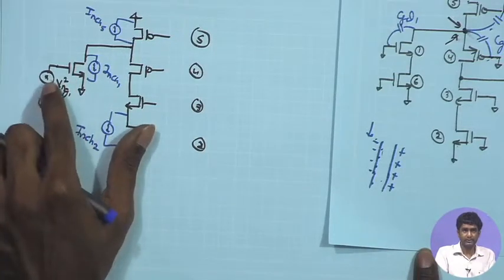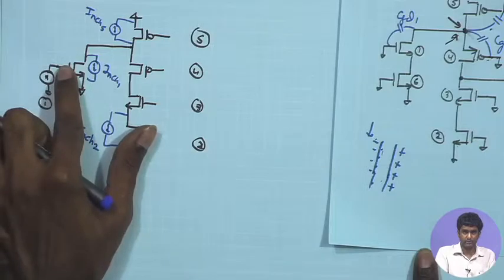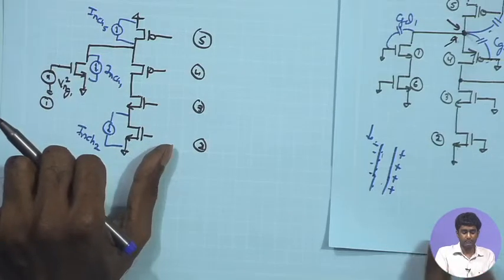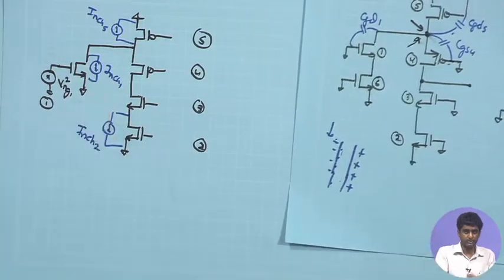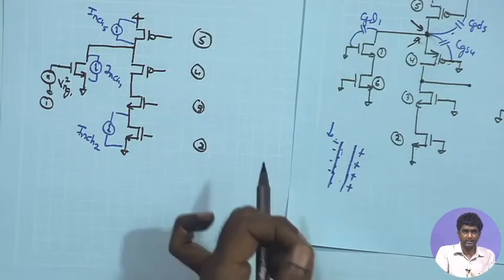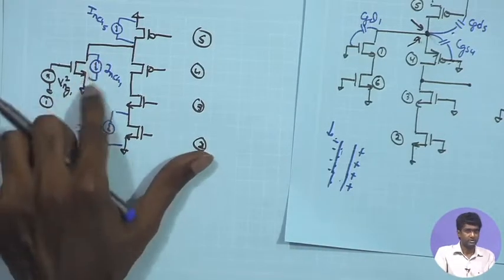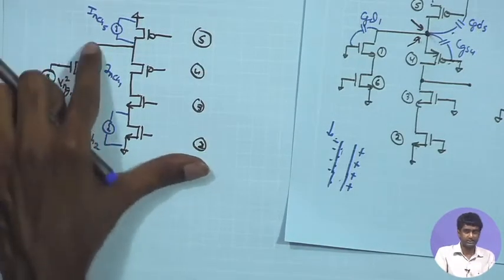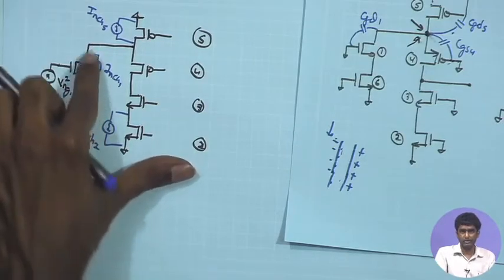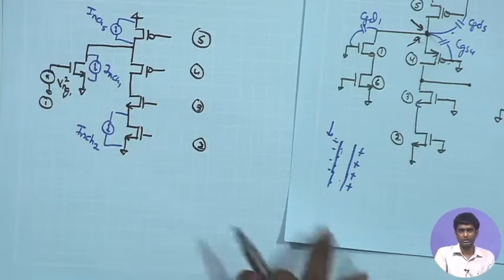That is why this flicker noise comes in series with the gate of the MOSFET, and so you can effectively see it as a noisy VT of the MOSFET, whereas the channel current noise comes because of the electrons transiting through the channel and having random fluctuation in the conduction path.